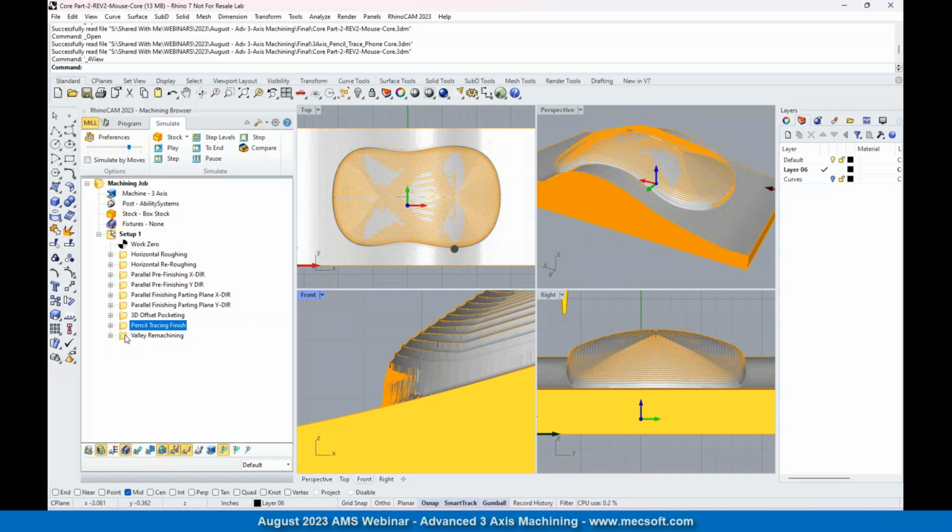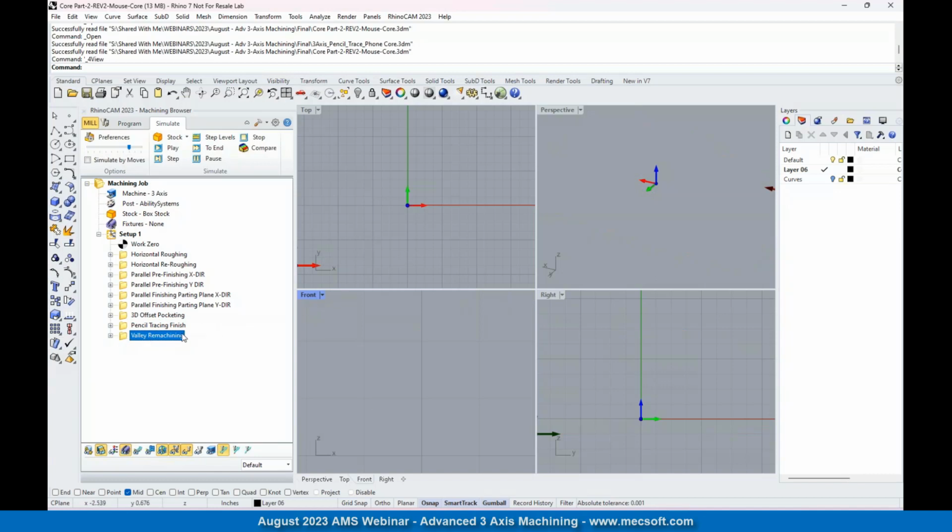And then one other note on compute speed, Don, was that taper tools notoriously take a lot more calculations, so taper tools will run slower than the standard straight ball mills. What we're demonstrating here is the power of the professional configuration, with a combination of both ball mills and taper mills to have as much control as you need for that tool on your geometry.